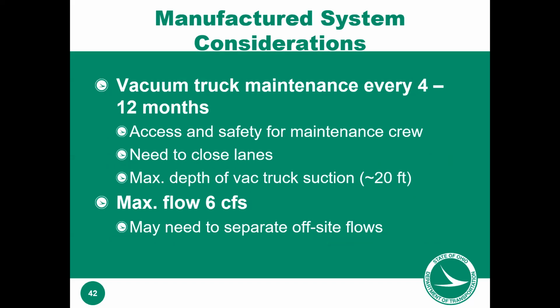These are really, really easy for your consultant that you're paying to put into a set of plans, and sometimes a little trickier to maintain, that you have to get down and vac every year. So you want to make sure you know what you're buying if this goes into your project. They can do a lot. They can remove a lot of pollution, a lot of trash, a lot of oil and grease. They have a significant value. But you just got to know that once you buy these, you're vacuuming them out forever.